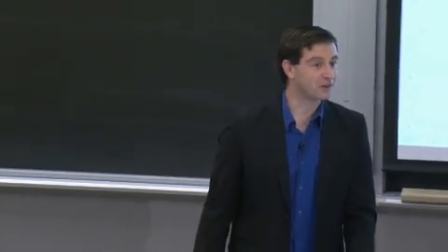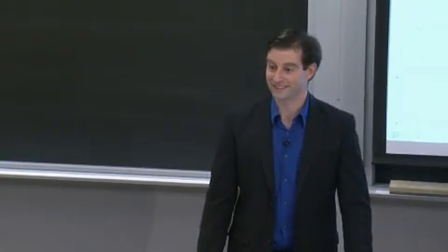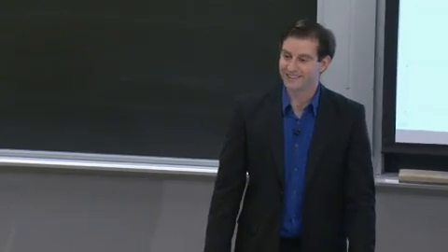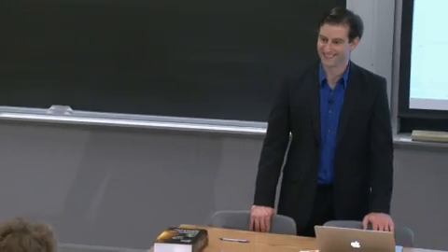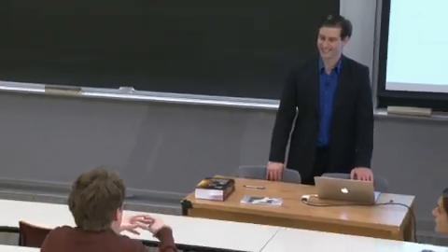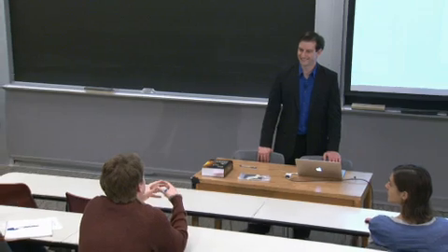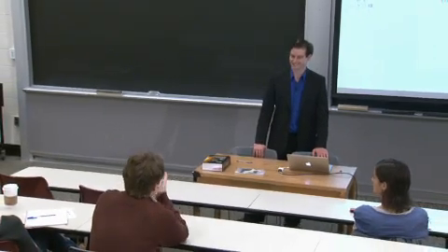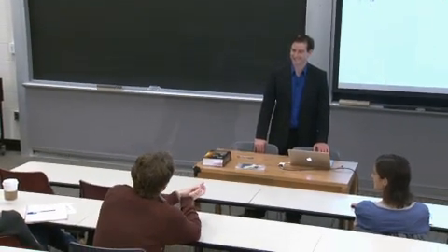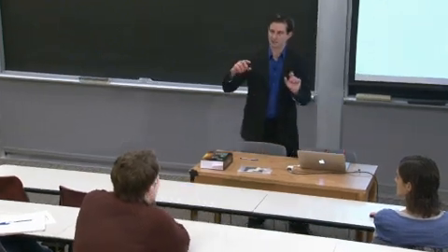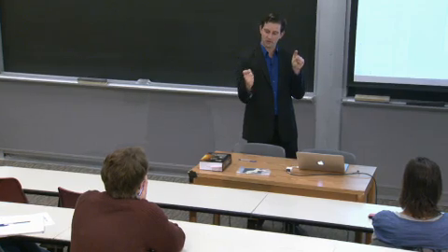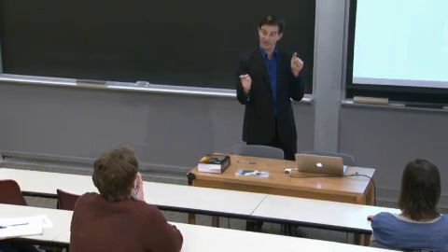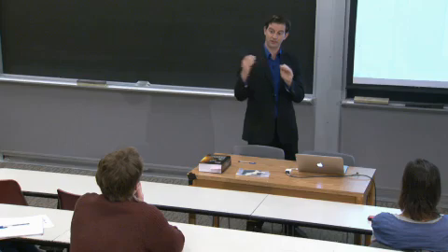Any other impressions that folks would like to share before we dive into the lecture? Yeah? So a question about carrier collection. Sure. How is it possible to extract any energy from carriers which are generated in front of the junction? Because even if they diffuse into the junction, they have nothing to fall down. Okay, so you have to think about it always from the perspective of the minority carrier. So if you generate an electron hole pair, your minority carrier is now a hole in the n+ region. That hole diffuses across the junction, the electron stays.